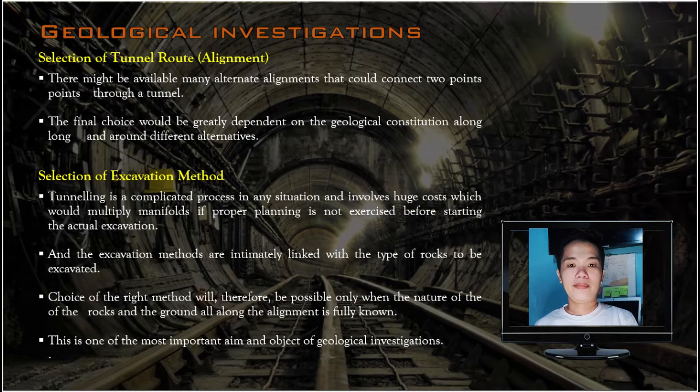Here are some of the geological investigations that need to be considered in constructing tunnels. Selection of tunnel route. There might be many alternate alignments that could connect two points through a tunnel. The final choice would be greatly dependent on the geological constitution along and around the different alternatives.